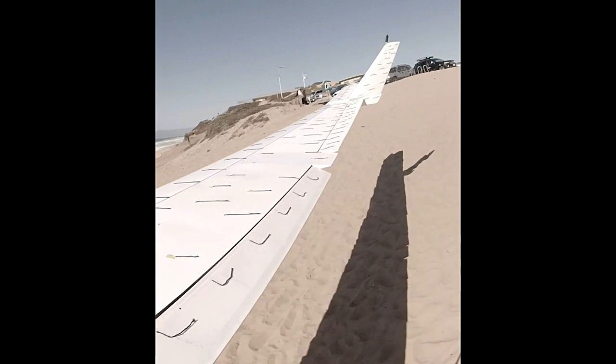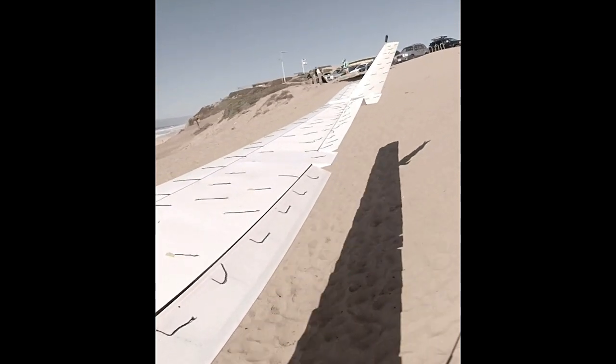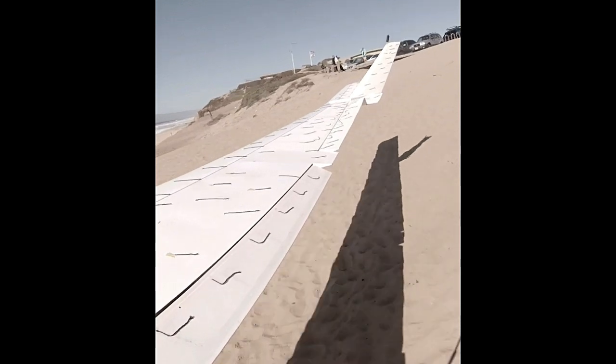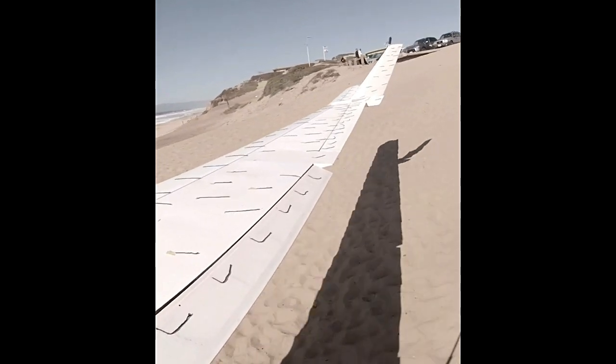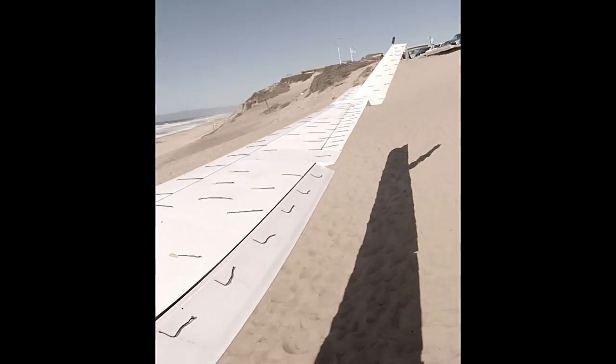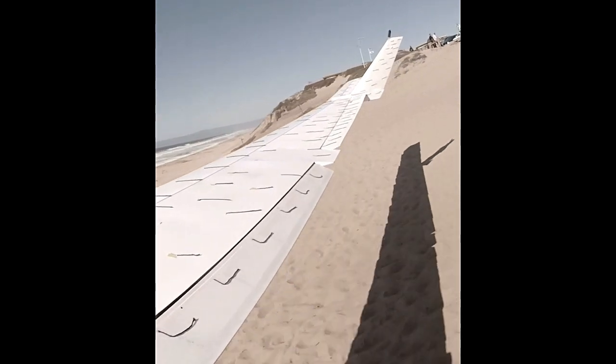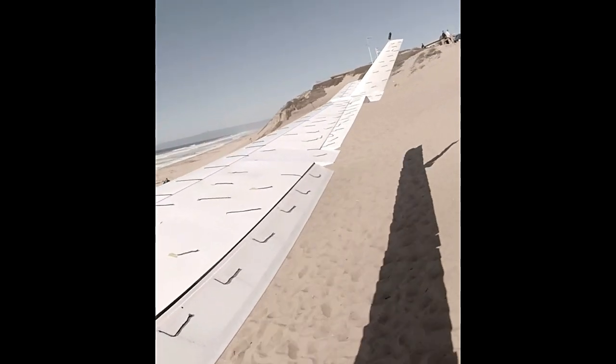And elevon comes back up. I'm top-siding the turn a little bit so I don't overbank. There's the start of a stall. We got a bunch of really messy flow there. Not helpful. And then right about here, I got everything neutralized, flows attached, and this is where I really started to scoot along.